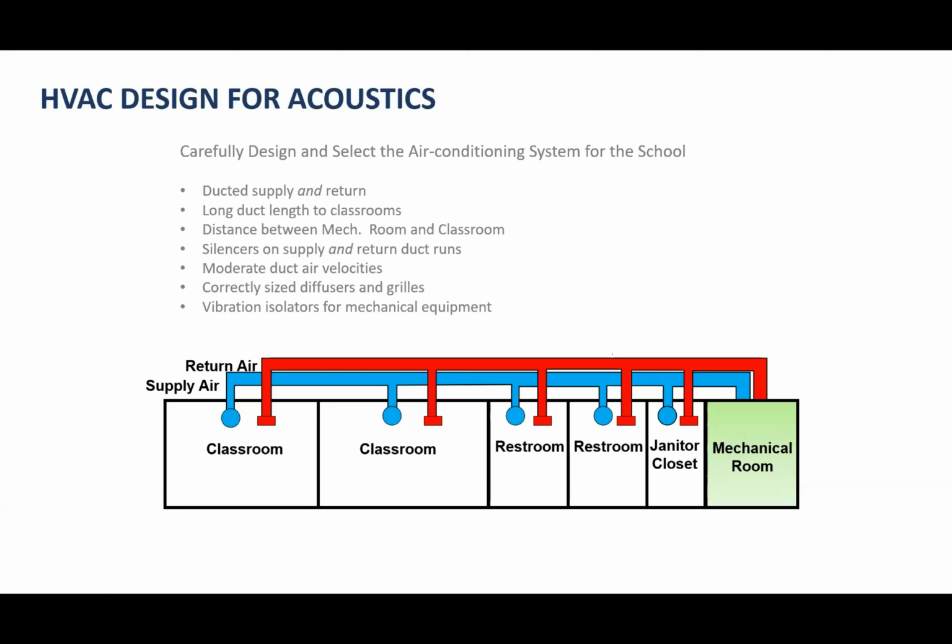Vibration isolation for the equipment is also critical. So spring mounts and spring hangers for the equipment are going to be very useful so that you don't have structure-borne noise being added into this as well.